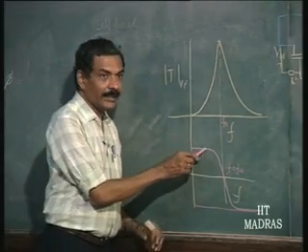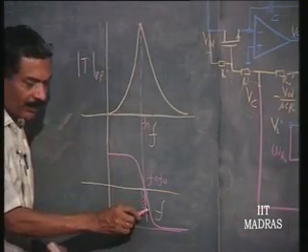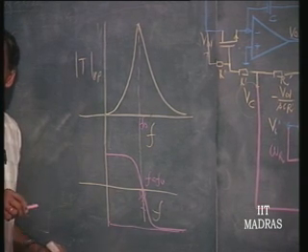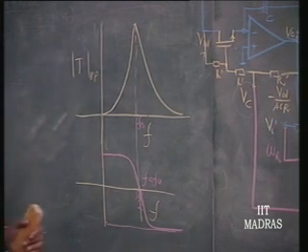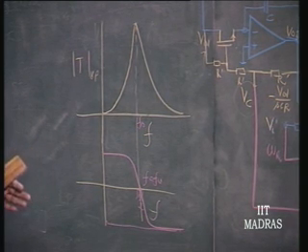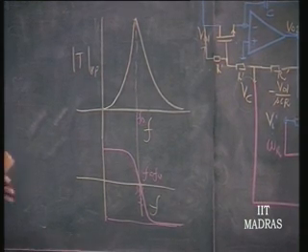So, the phase variation of this, if you plot, we have already plotted it here. It is going to vary in this fashion. This is going to be pi by 2. The initial phase variation is primarily determined by the numerator rather than the denominator, because S is j omega r and omega r is very small.